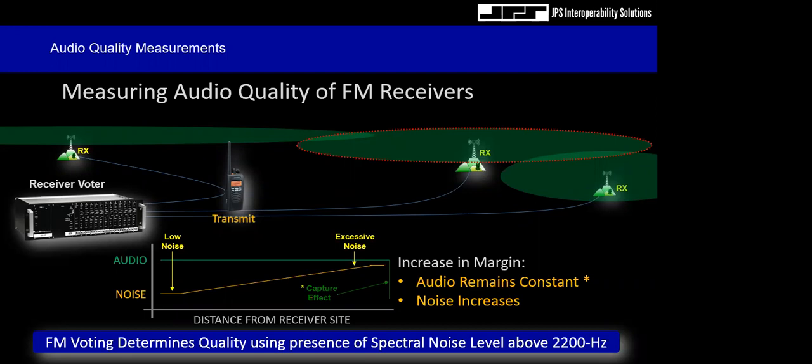Something you'll want to observe as you pass over the mountain pass is that the audio, for the most part, stays constant. The amplitude stays constant until I crest the pass, and then the audio drops away immediately. We call that the capture effect. We'll talk about capture, capture ratio and the non-capture region a little bit later once we start talking about simulcast.